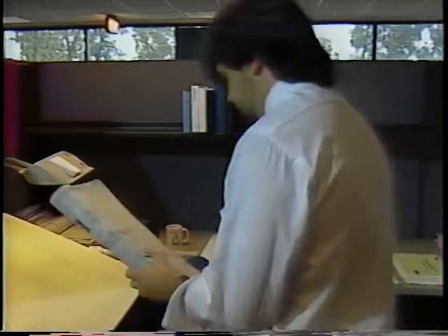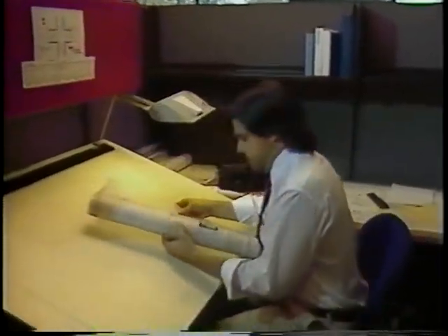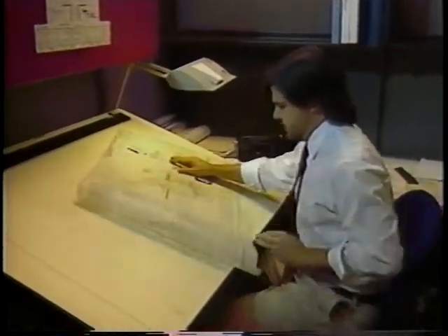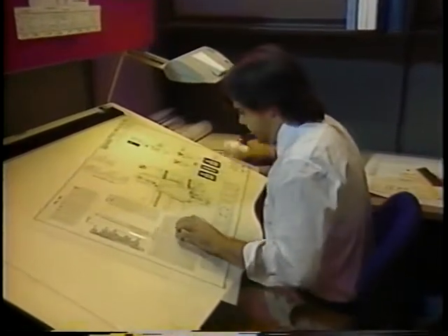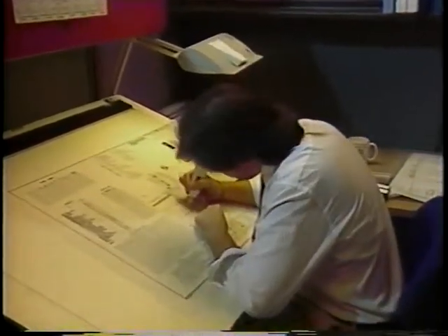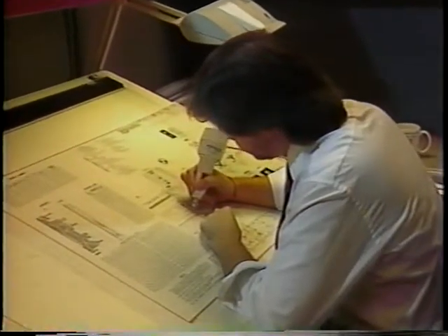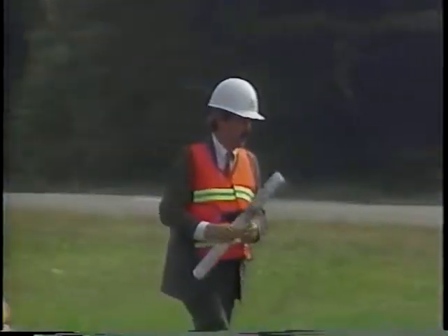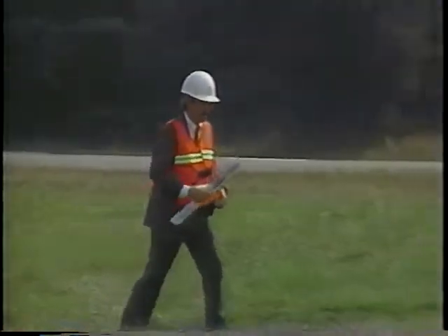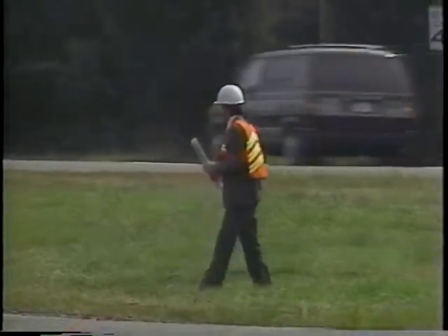The completed drawing should be reviewed with the design engineer. This ensures that the loops or probes are located as specified in areas free of any underground hardware that could interfere with detector operation. Prior to finalizing the scale drawing, make a field visit to the location. Once on site, inventory the existing conditions and identify any potential problems.